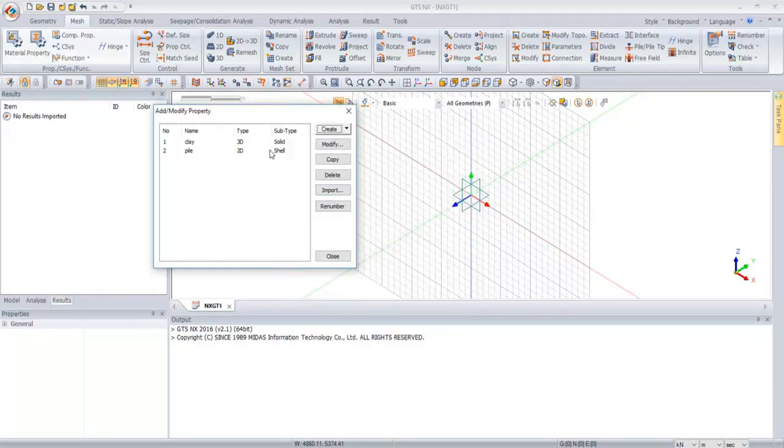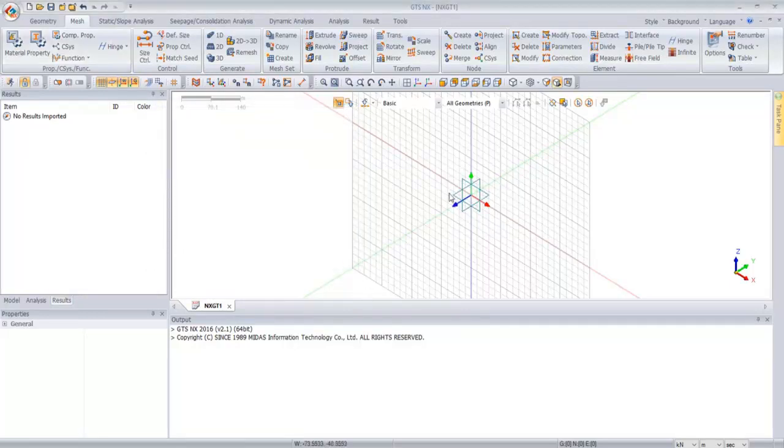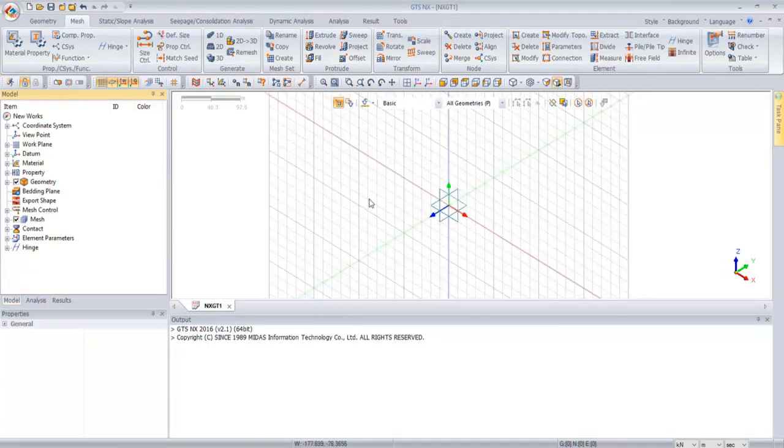So right off the bat, that's one of the differences from where we depart from the Plaxis tutorial, if you're familiar with it or not, but they actually don't model the pile as a structural element. What they end up doing is using an object, a geometry, a rigid object as they call it, and so it has no structural properties.